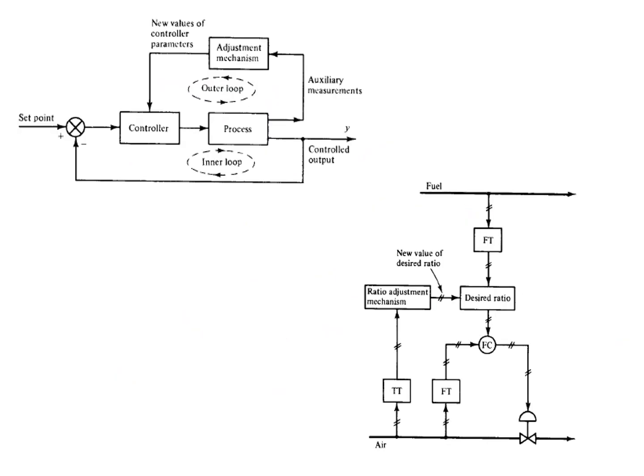So this is programmed, or scheduling, adaptive control. Let's see how it works. This inner loop is a normal feedback process. Say, for example, this process is non-stationary, or a non-linear process which introduces some different characteristics in the process. So what we do is we take an auxiliary variable and measure that auxiliary variable.